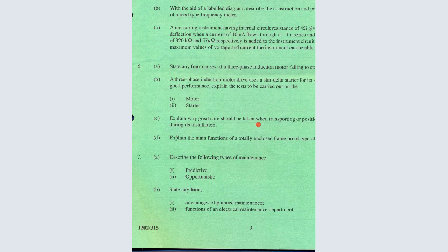Is it the same as corrective? Opportunistic maintenance is when you take an opportunity of maybe doing something, then you do maintenance. You take an opportunity when the factory is not on demand, or the production is not highly demanded, and then you schedule a maintenance. Or maybe a motor has broken, then you are replacing the motor, and at the same time you do maintenance. So that is opportunistic. You do the maintenance because something has occurred.